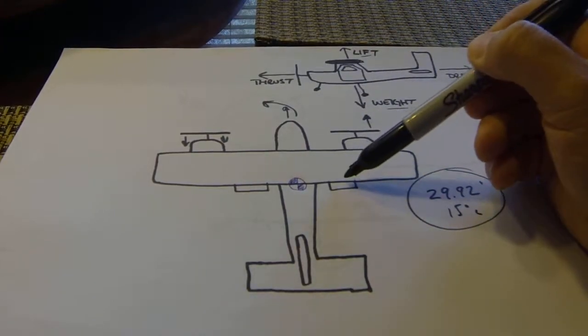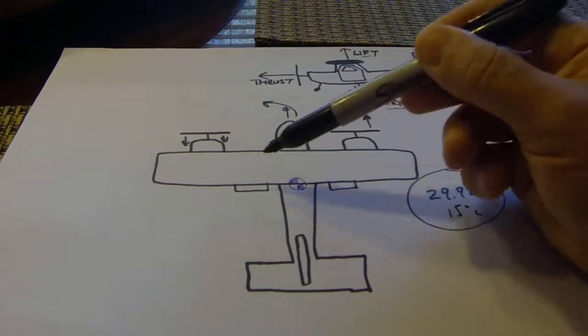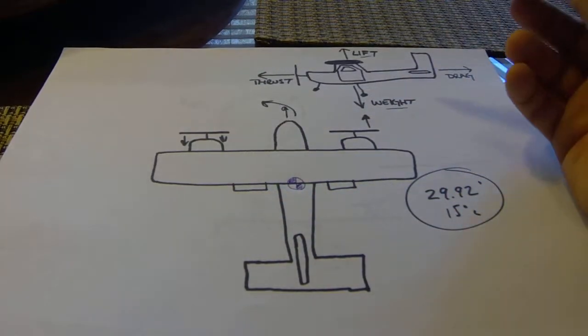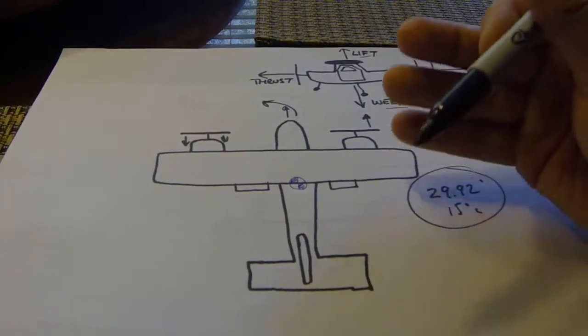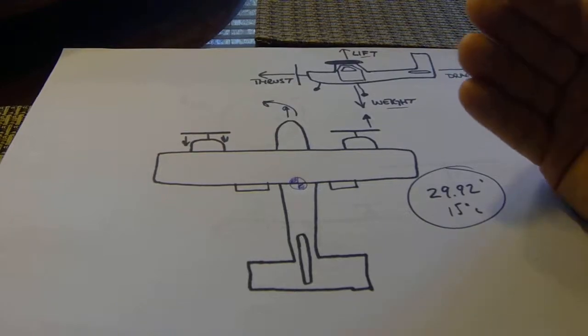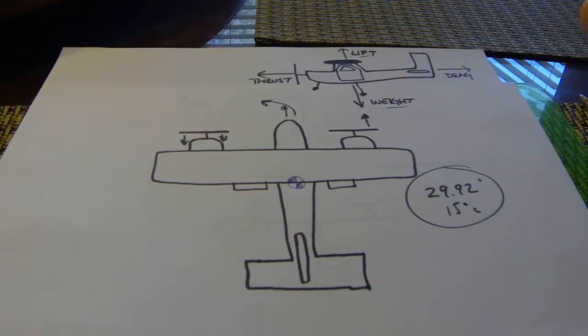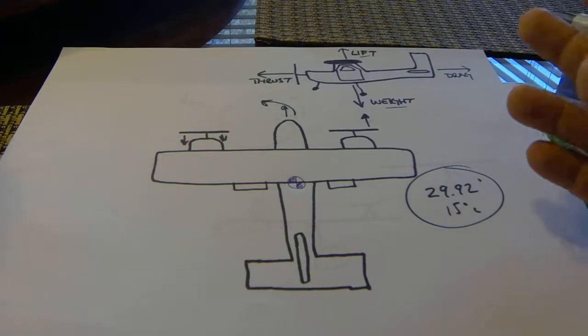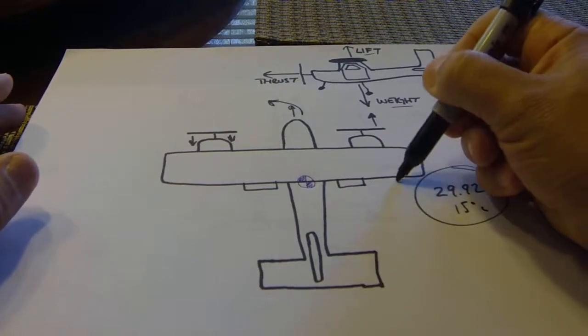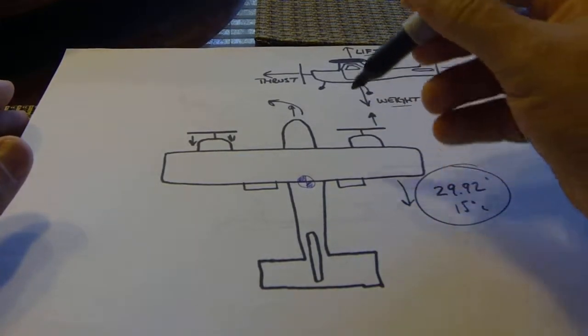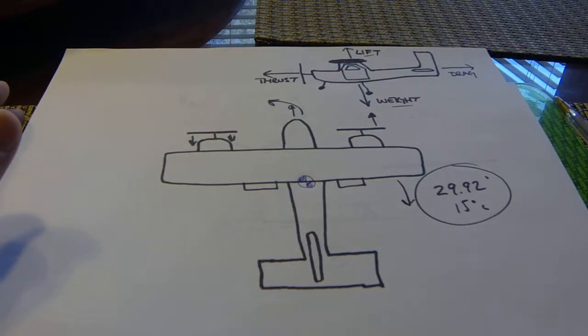We would put down just the operative side and leave the inop side up, but we can't do that. So if you put the flaps down, we're creating drag. We're creating kind of like the gear extension before that I mentioned. We're creating a stabilizing effect. We're pulling this wing back this way by creating that induced drag.